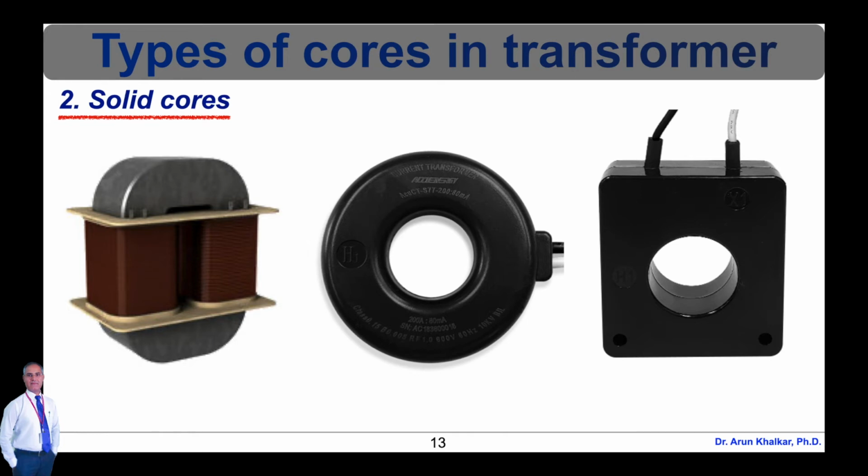Powdered iron cores are used in circuits such as switch mode power supplies that operate above mains frequencies and up to a few tens of kilohertz. These materials combine high magnetic permeability with high bulk electrical resistivity. For frequencies extending beyond the very high frequency band, cores made from non-conductive magnetic ceramic materials called ferrites are common.